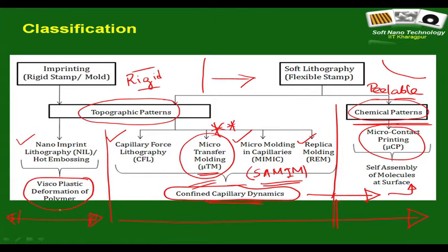It is not a capillary driven flow, and that is in fact this mechanism, as I mentioned once briefly, necessitates you to use a rigid stamp, because since you are applying a significant amount of excess force to cause deformation of a softened or molten high viscosity polymer layer, you need a lot of pressure to cause deformation, and unless you have a rigid stamp, you apply the pressure over a flexible stamp and the stamp is simply going to collapse, it is not going to lead to pattern replication. So, these are the issues.